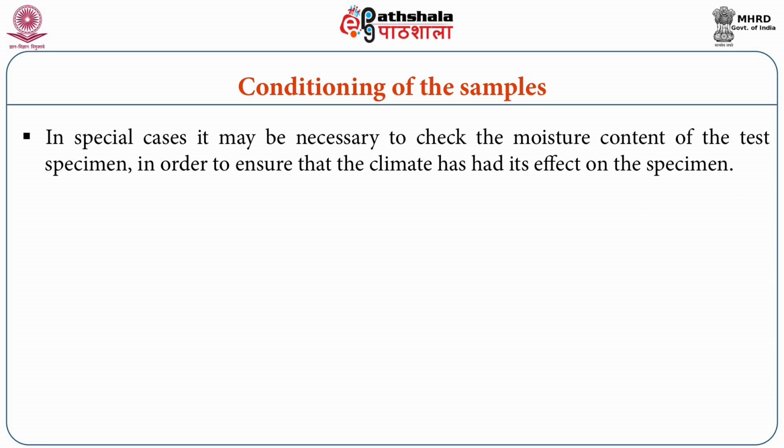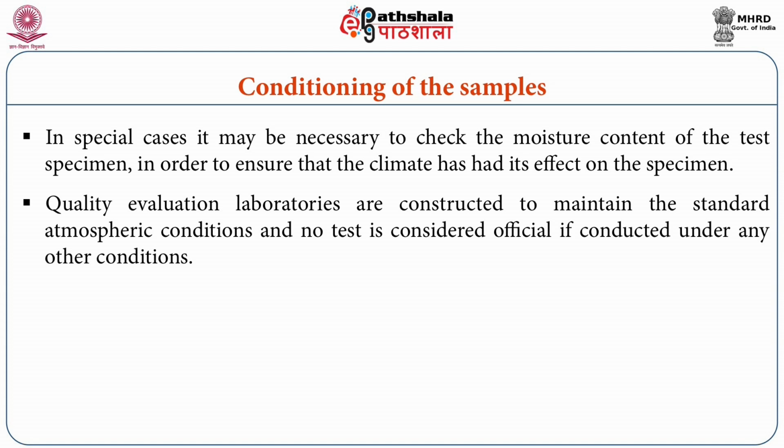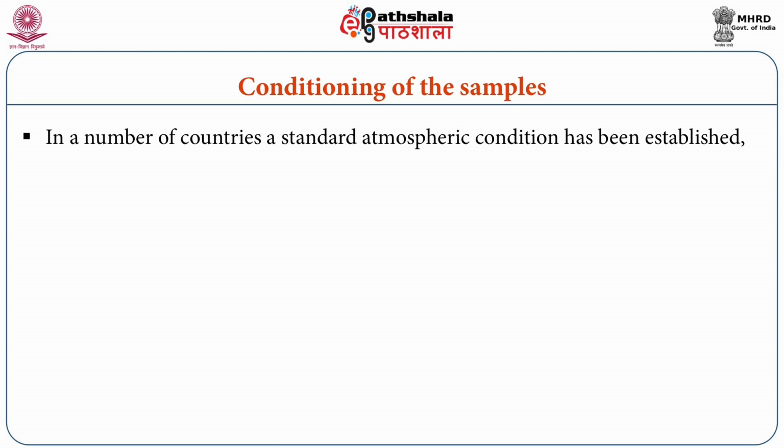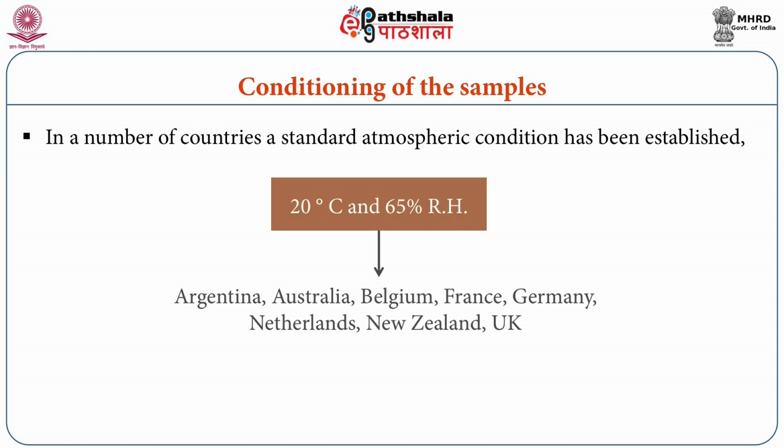In special cases, it may be necessary to check the moisture content of the test specimen in order to ensure that the climate has had its effect on the specimen. Quality evaluation laboratories are constructed to maintain the standard atmospheric conditions, and no test is considered official if conducted under any other conditions.